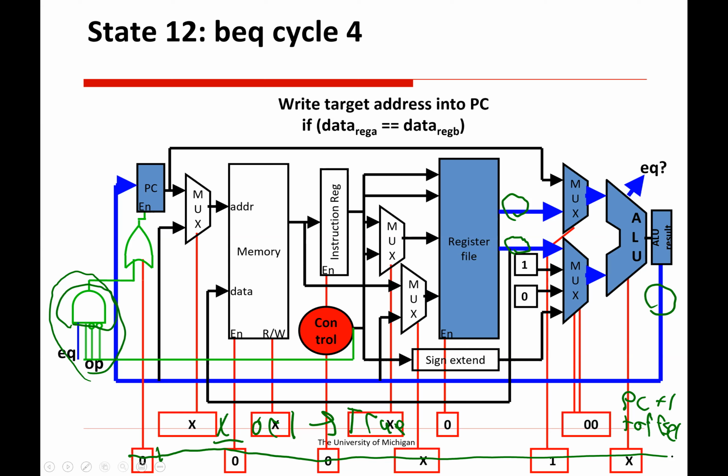Allison asked, how is the ALU register not being overridden when register A and register B change? I think I answered that now. It is being overwritten, but at the same time that we're overwriting it, we're taking the good result and storing it into PC. As long as we're moving the values forward, it's fine. It's good to get this because the next processor type we're going to talk about has a bunch of these registers all in a row, and we're continuously passing them one to the next. This is called pipelining.